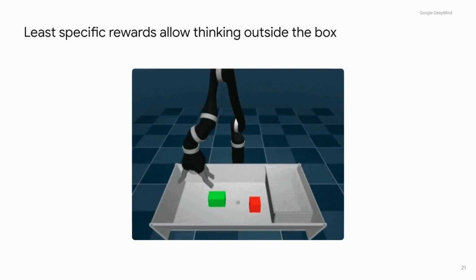Here's a robot arm that needs to clean up. It needs to put these little objects into the box here. It has a lid, so it has to open the lid and then put the thing in. If we come with our engineering goggles on, we would say, okay, I put coordinate systems at the end effector, I make it so that the distance to the grasp points gets smaller, and I forgot I need to open the box, so let me use the fingers to open the box first, and have a little state machine, and then if that's successful, I go and take the block and put it in there.